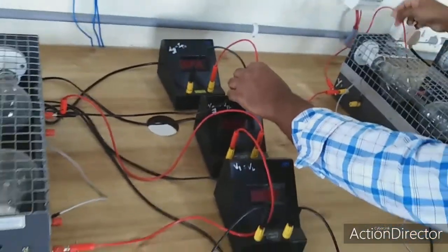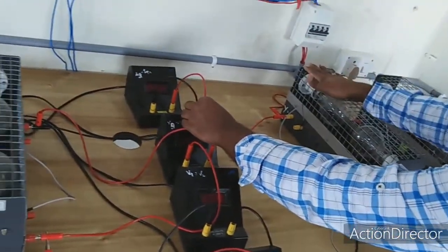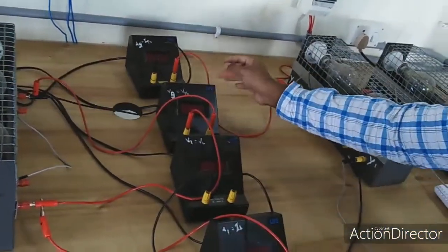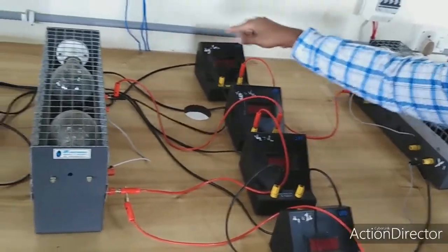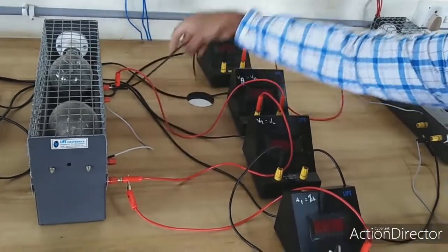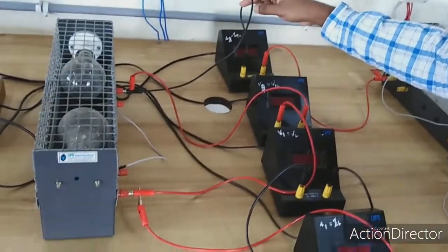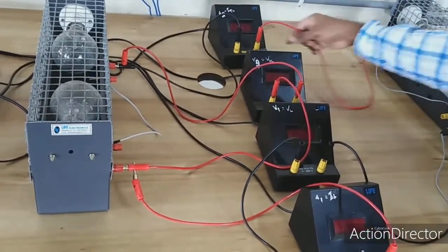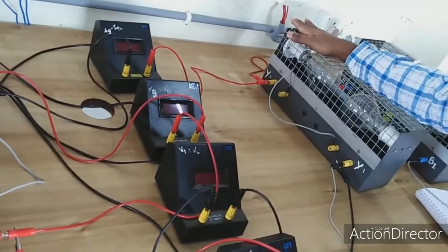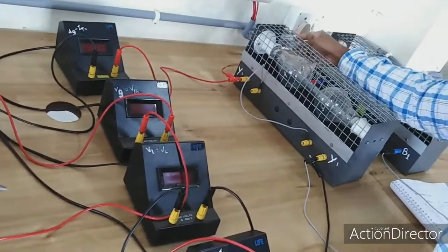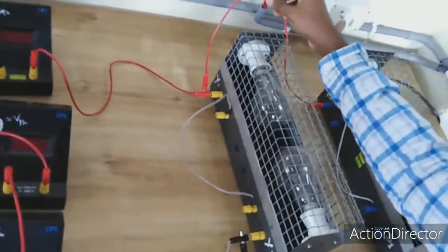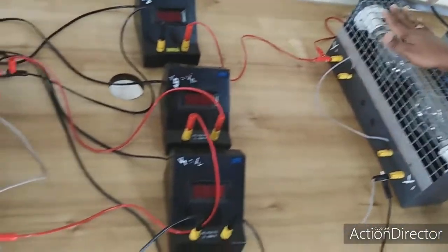So now the last one is connected to the second load end point, and this also should be connected to the first load. In between, I am connecting an ammeter. From the first load end point to the ammeter, I am connecting to measure the phase current, and this is connected to the end point of the Y point. Then to form a neutral point, I am connecting the B phase terminal to the end point of this end connection. So like that I am forming a neutral connection.